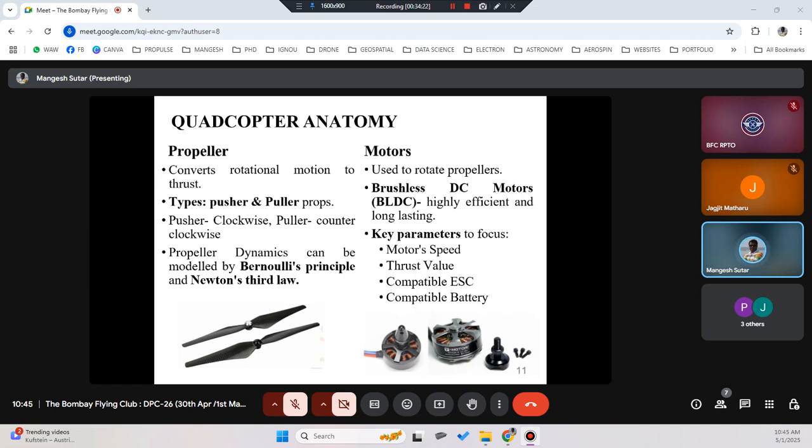Okay, this is the new study that has come up, and every time you will come up with a new way of doing things. So that's how you design the drone. You start with motor, propeller, then ESC. The rest of the other things are just passive devices, like the body which houses your electronics, a compartment under the body for the battery, or a connector where you will connect your gimbal and your payload, like camera or thermal